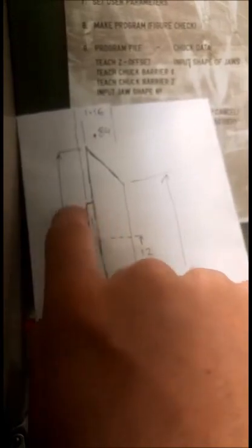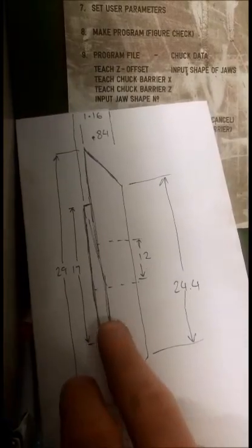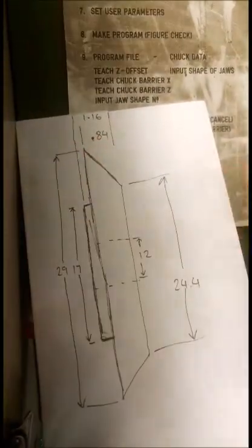Number of grooves. So if you're doing multiple grooves, this is where you put that in. I'm only doing 1. The pitch, seeing as I'm only doing 1, there is no pitch. Groove width, so I'm using a 3mm grooving tool, but what I want to do is groove that 3mm, because I'm going to get down to this step here, but then I need to leave enough so that I can run the tool in to actually part off. So that's about another 0.5 on there. So I'll groove this to 4.5, so that'll give me enough room to do that finishing one.